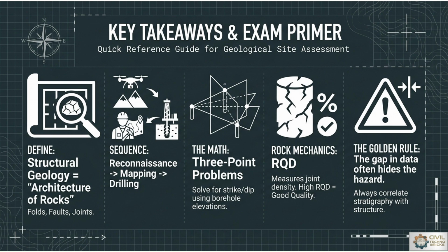Higher rock quality designation is equal to good quality, and the golden rule is that the gap in data often hides the hazard. So always correlate stratigraphy with structure, means we have to construct each and every structure based on the stratigraphical data which is beneath the earth surface. So subsurface geological exploration is the most important phenomenon with reference to the construction point of view.